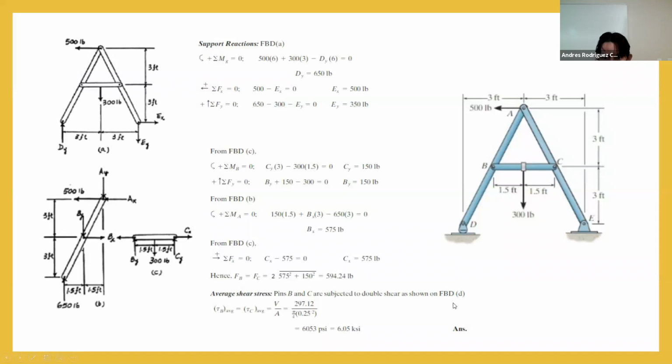So where we were. So the average is going to be obtained like this one in here. So we got the area of the pin that is here, and we got the shear that we already obtained. This shear is going to be this guy here divided by 2. And this shear is obtained by Pythagoras here. So it's very easy to obtain right now what kind of internal force that we are going to have inside of the element, considering that part. Is that clear? Or is it a little bit?